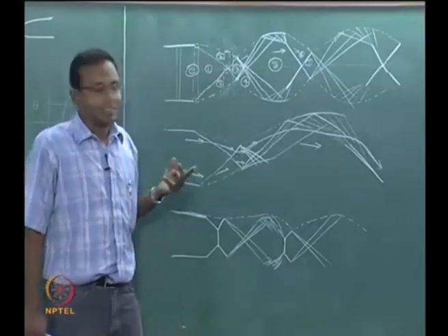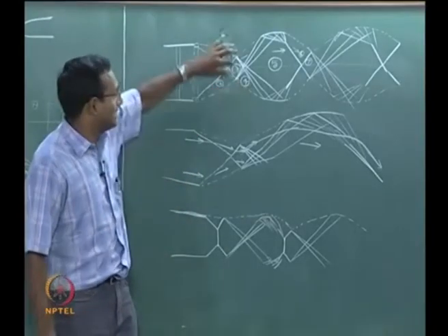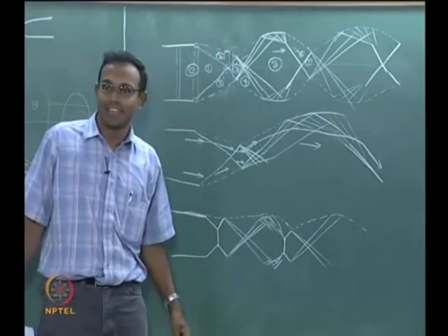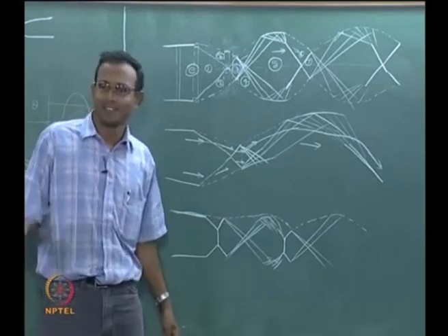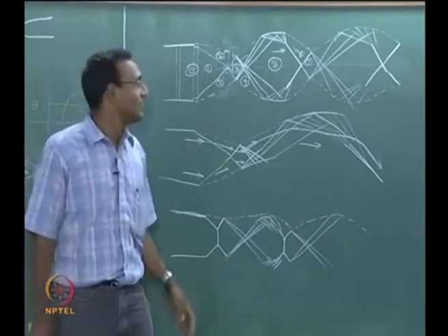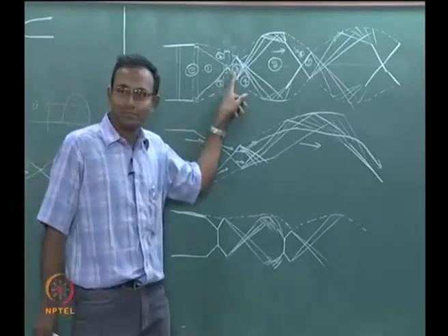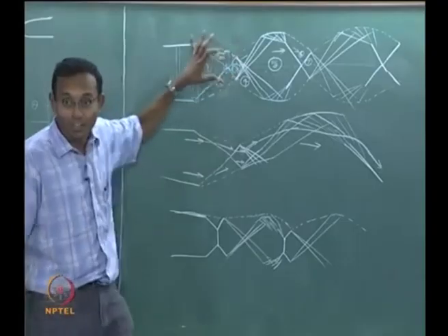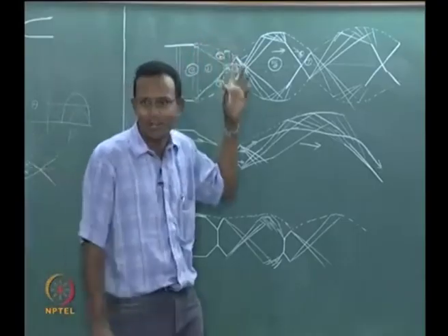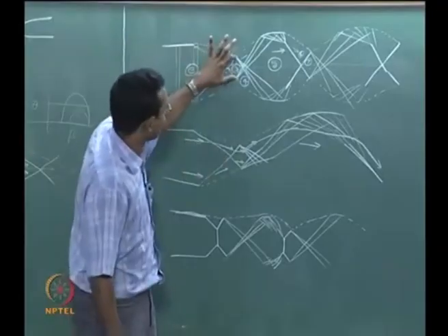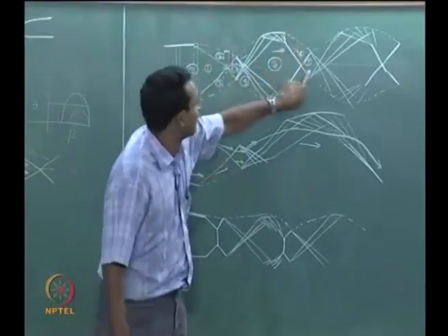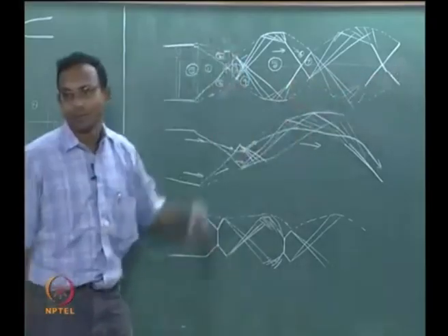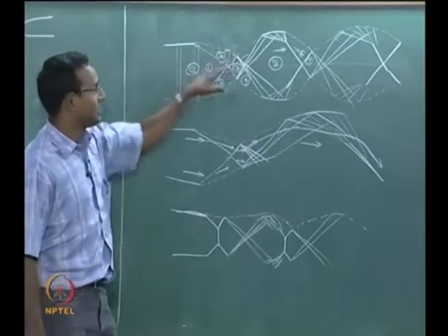Okay. This is the kind of glow you will see as diamond shaped glows behind your supersonic jets at takeoff. You would see that in SR-71 typical pictures, which will be available on the web if you want. Just go look at it taking off. You will see these diamond like structures just behind it which are glowing hot. Okay. Typically they will be glowing orangish yellow. This portion will be glowing hot, then the region 7 will be glowing hot, then 8, 9, 10, 11 will be glowing hot, like that it just keeps going. Okay. The other regions will be cold.